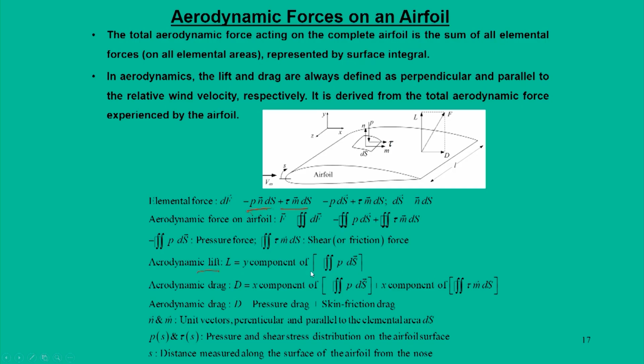shear force. Why do we not say that lift includes the shear term? Because the effect of shear stress in the y component is very small compared to the pressure force. That is the reason the aerodynamic lift mostly comes due to the pressure force, that means the pressure difference between the upper and lower surface of the airfoil.